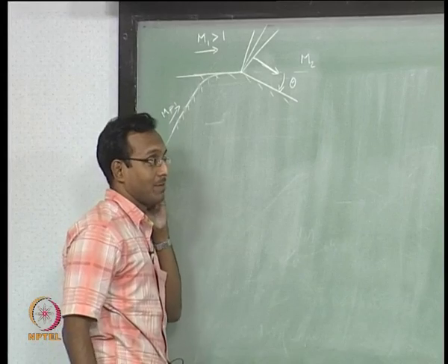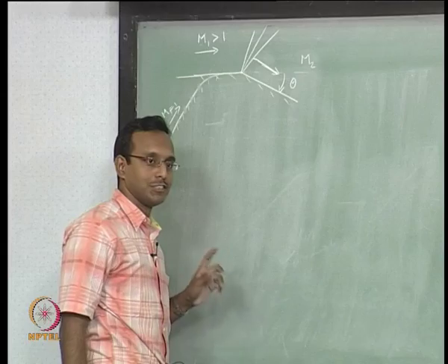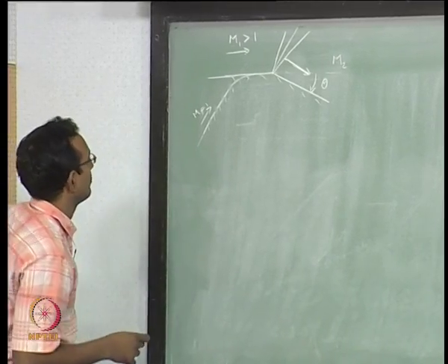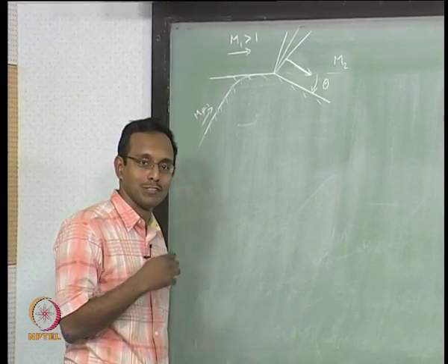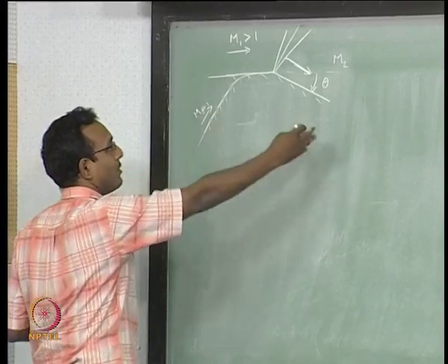By the way, the Prandtl-Meyer function is a monotonic function. It is not going to go up and down, it just keeps on increasing. That is one more important thing you should know. But as it goes to very high Mach numbers, the number does not change much, it is going to asymptote to a particular value. But this is how you have to think about it.